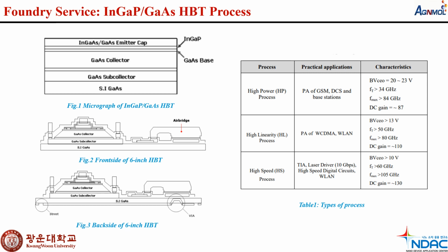A chip process considers not only one surface but also the front and back sides. The front side is fabricated first, then the back side is treated. Figures are given to illustrate each part in the following explanation. In figure number 2, we can see the configuration of the 6-inch HBT frontside flowchart, and in figure number 3, we can see the 6-inch HBT backside flowchart and its configuration.